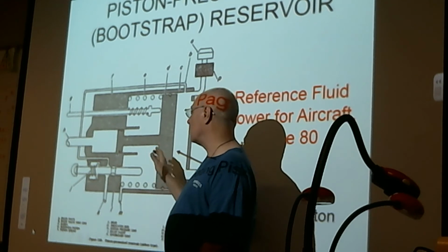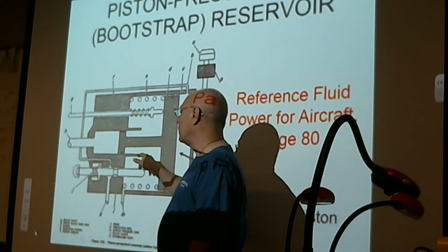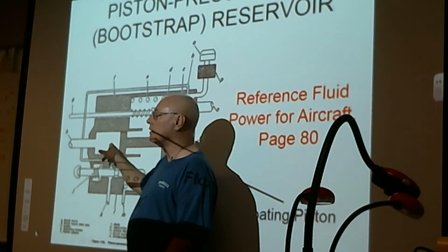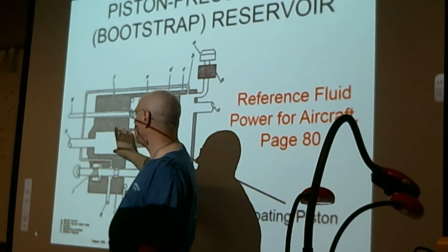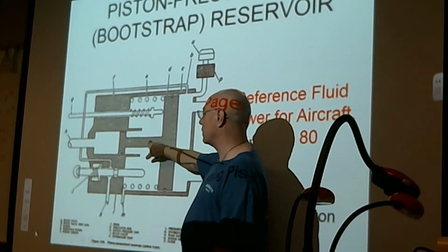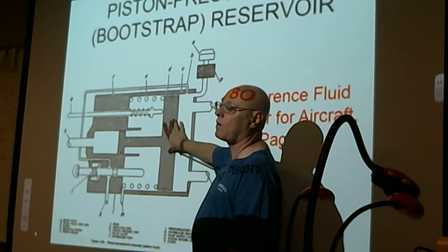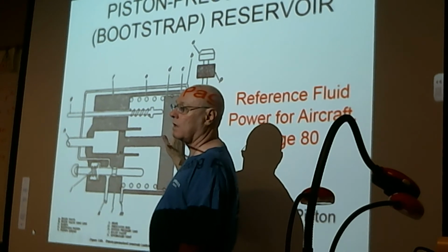Oh, you may ask yourself, what was the actual force that's pushing or bearing against this piston? It's actually system pressure. What they do is they tap off of system pressure in the pressure manifold. It pushes on a smaller diameter piston. That force is translated to a larger piston by a rod that connects to it. So it cuts the amount of pressure that's available on the fluid.